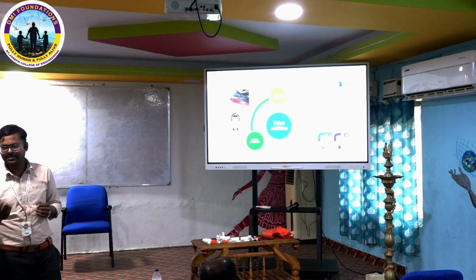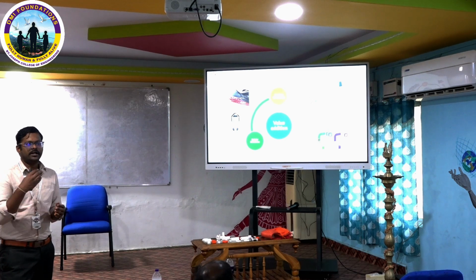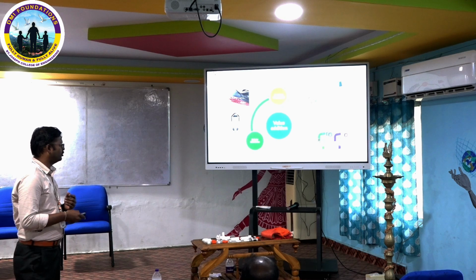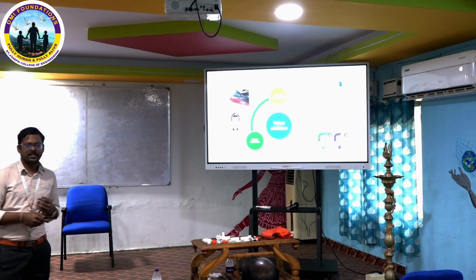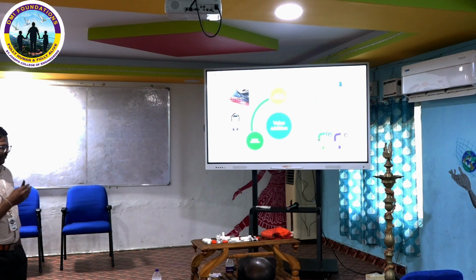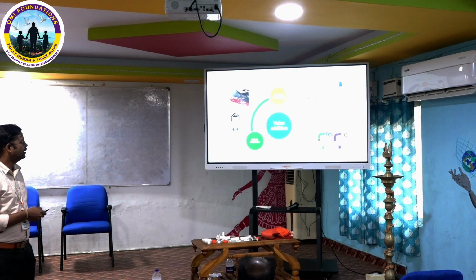Next one is part consolidation, which I already explained: reducing the number of parts while getting more efficiency compared to the previous product. Third one is cellular structures. Cellular structures are structures which have material only where the stress concentration is going to happen. In the further slides we are going to see only about cellular structures.